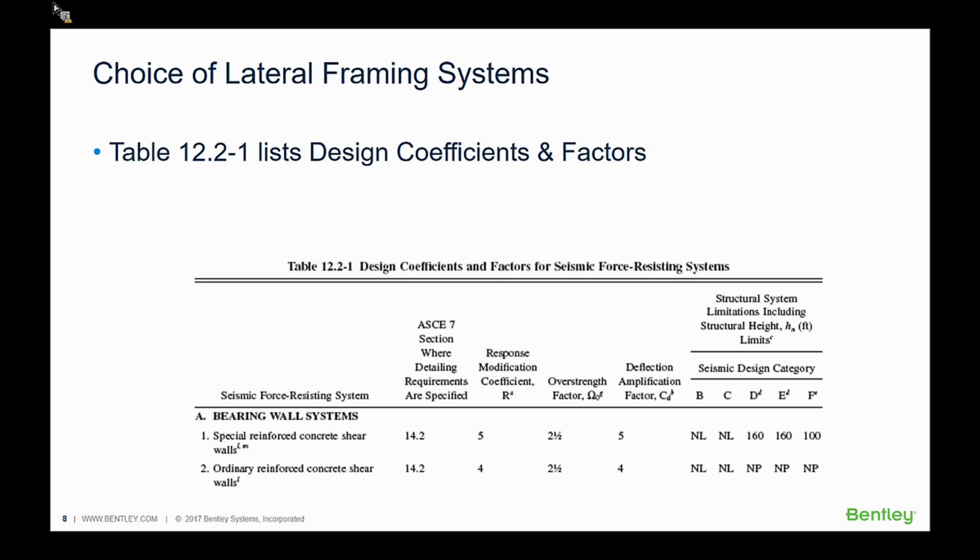Knowing these coefficients is important because no matter whether you are using a static analysis or a dynamic analysis, these are directly used as inputs for calculation of the design base shear. The table also imposes some limits on using certain seismic force resisting systems within certain design categories. So for example, as seen in this slide, one can use special reinforced concrete shear walls in